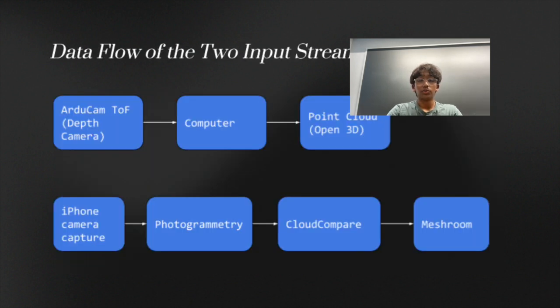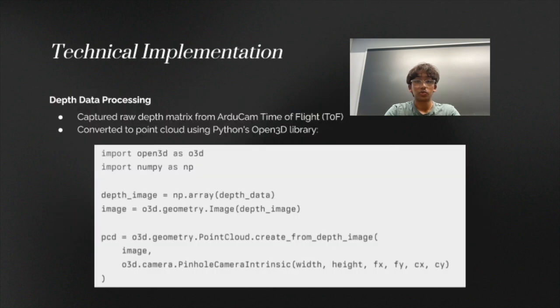The first input stream, we used the Arducam TOF, which was the depth camera. Our first technical implementation was basically taking a raw depth matrix from the Arducam TOF and then converting that into a point cloud using Python's Open3D library.